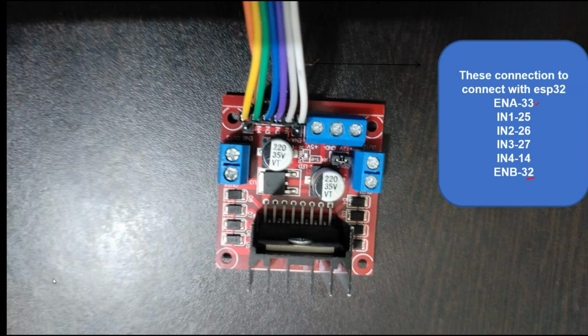Okay, take a female wire and cut that into 2. Okay, and then join with the switch, the other end to the positive of the battery, because they are going to use 9-volt battery. Okay, it is a 9-volt battery for this people. And then another wire you have to join like this. Okay, and then you have to connect the motor like this, red line to one wire. Okay, this is one wire that has been connected with a red line. Okay, and this is another wire that has been connected with the black line of your motor.